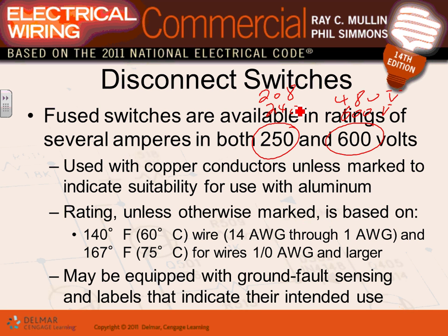Any comments, guys, about the voltage rating of the switches? Comments about the voltage rating of switches? If your system is 208, your switch can be rated for 250, right? Slightly higher than what your voltage is. All the terminals for the switches, guys, are rated for copper unless they say otherwise.